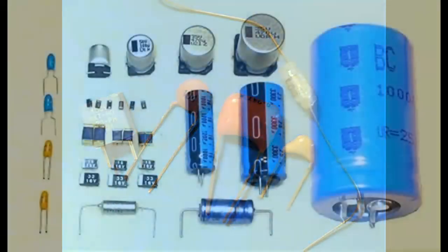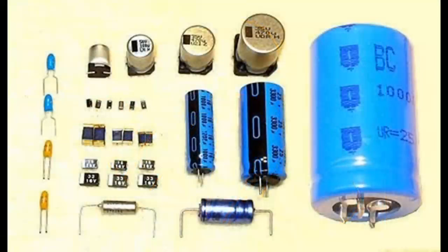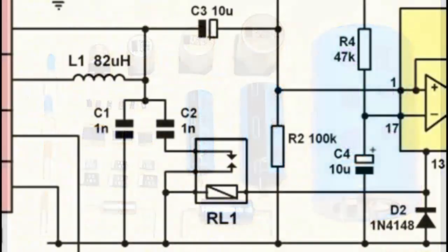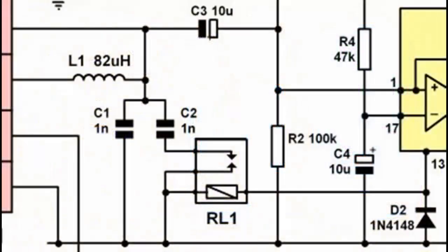Polarization is mainly limited to electrolytic and tantalum capacitors, and can be easily seen with the respective markings on the component body. In some circuits it may not be obvious which way around an electrolytic or tantalum capacitor should be wired. This can be found by tracing, or looking on the circuit diagram, to see which part of the circuit that connects to the capacitor is more positive than the other.